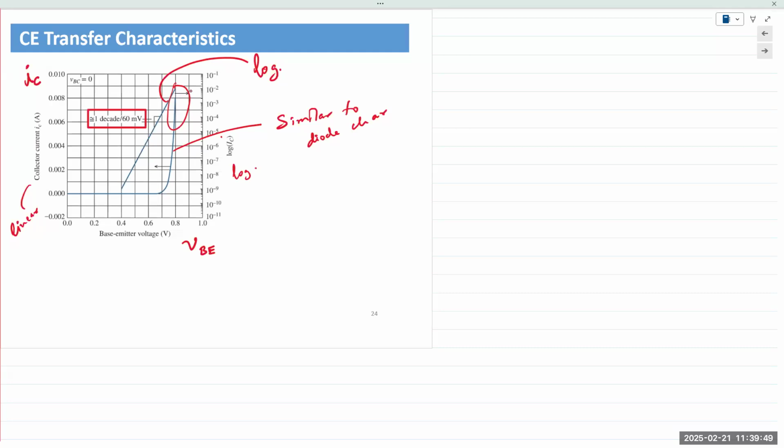Well, collector current is a factor in the emitter current. They're almost equal. Except for the base current, collector current and emitter current are almost equal. So if IC is beta times IB, IE is IC plus IB. So it's beta IB plus IB, so IB times 1 plus beta. But again, going back to that earlier point, we only look at the equation of collector current as a function of the base current. IC is a function of IB, but then IE is also a function of IB.